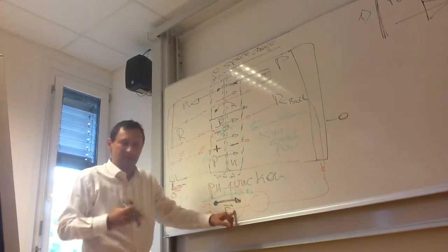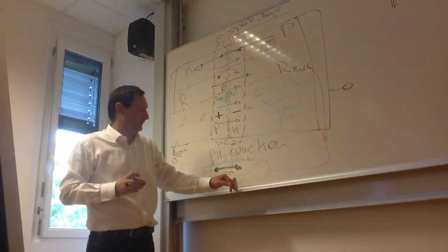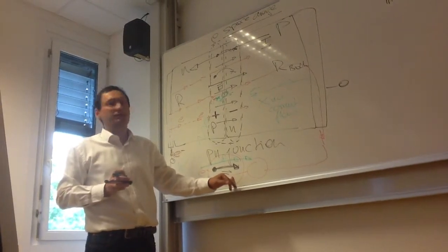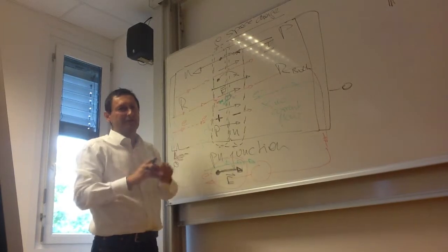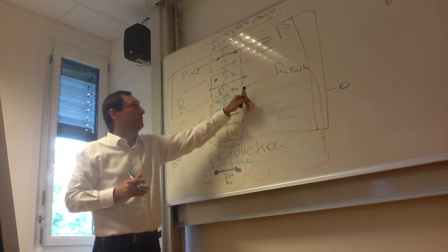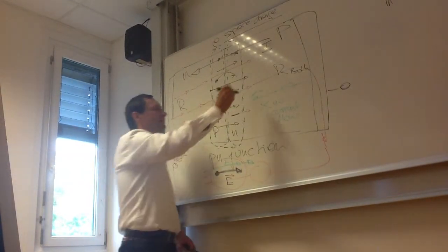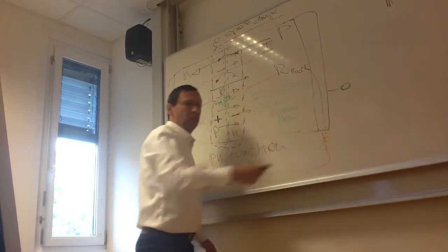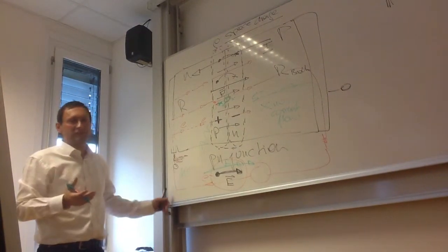Due to this diffusion potential or the inner electric field of the PN junction, this charge carrier pair gets separated and it gets out to the boundaries of the space charge area, and there it can freely move through the bulk material, and that's what we call a generator.